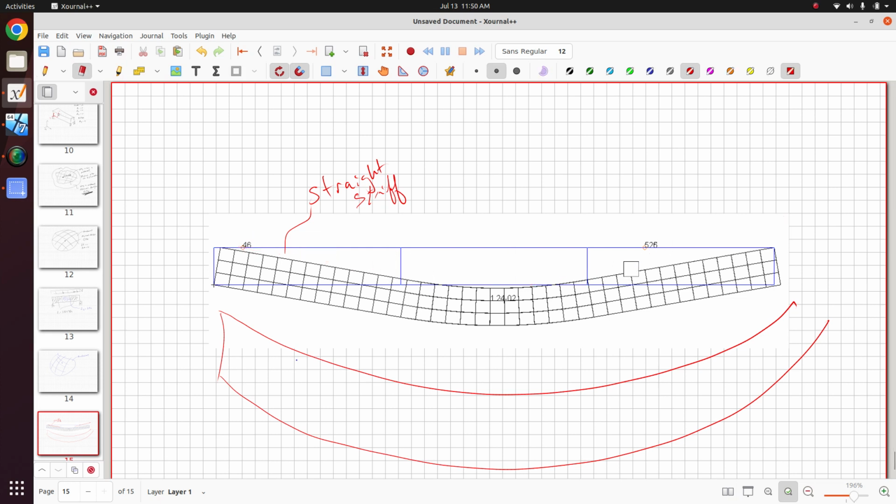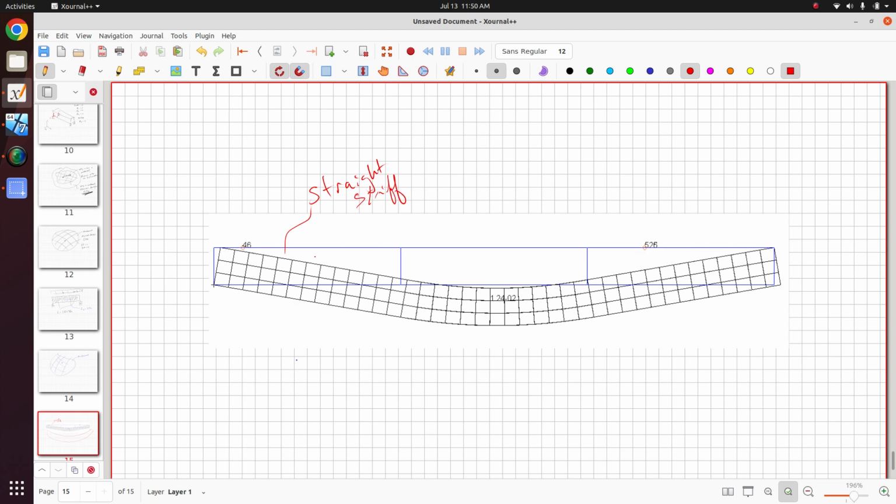So you can see in this mode shape, it's very subtle, but some of our structure is very stiff, while the other part of the structure is actually very soft. So here, if you remember, the stiffnesses were 200E9 pascals, and the other one was 2 pascals. So here I like to joke sometimes that, okay, this is steel, but this is jello.